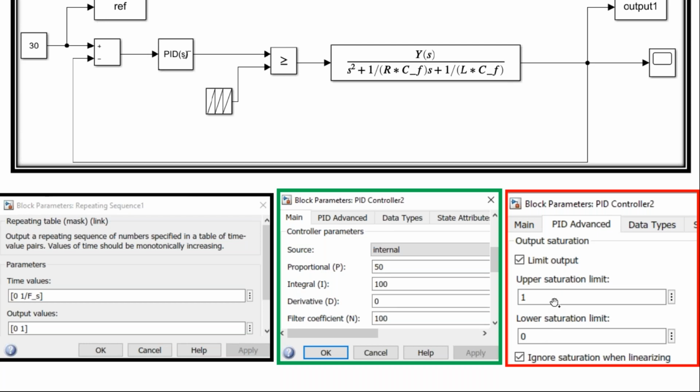What I can say from here is that if you use the PID control auto tuning, it will not work in this particular case. There may be several reasons. One such reason is that it has a lot of non-linear terms. This is a non-linearity, and this is a non-linearity. Due to that, it is not working. So based upon intuition, you can completely remove these two blocks, try to design a PID controller, and later you inject these two elements and tune manually to get the desired response. That is the way to do this.